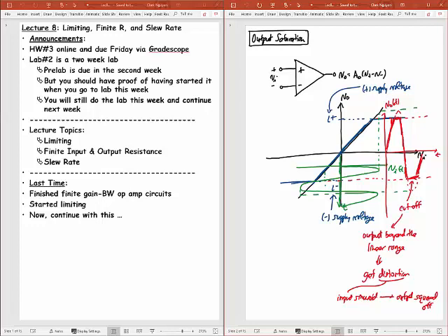And if my op-amp had no offset voltage, which means it's ideal in every respect except for output saturation, then what I would see is an input signal coming in here, and if it's too large, then when I project that input signal onto the transfer function for the op-amp, so the VTC, it would project to some point beyond where the op-amp transfer function actually exists, which is the blue here.